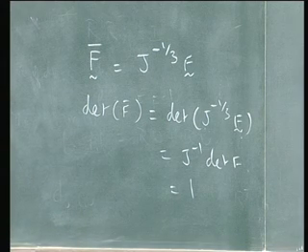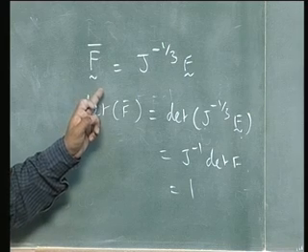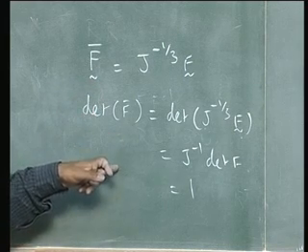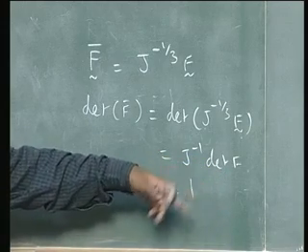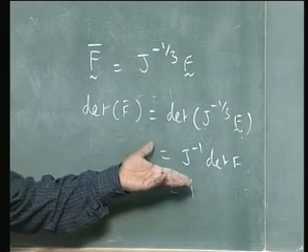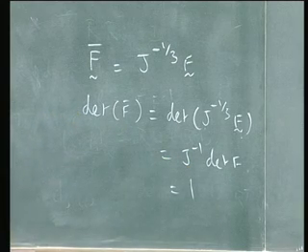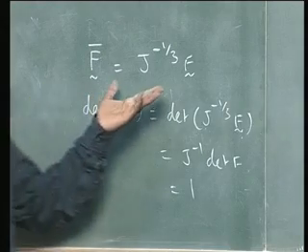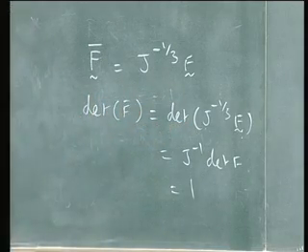So what does it mean? It means that F bar is the one which is responsible for the deviatoric part, and when there is incompressibility, the determinant of F, or J, is equal to 1. We can split F into two parts: the dilatational part and the deviatoric part.